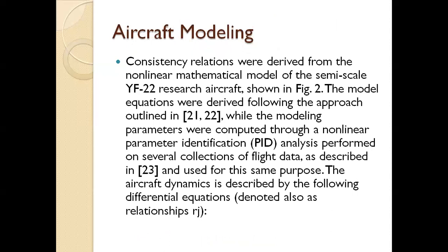Aircraft modeling. Consistency relations were derived from the nonlinear mathematical model of the semi-scale YF-22 research aircraft. The model equations were derived following the approach outlined, while the modeling parameters were computed through a non-linear parameter identification (PID) analysis performed based on several collections of flight data.